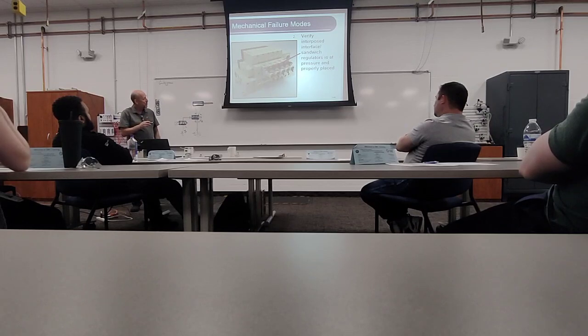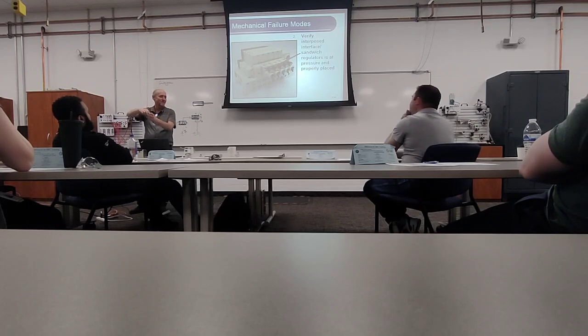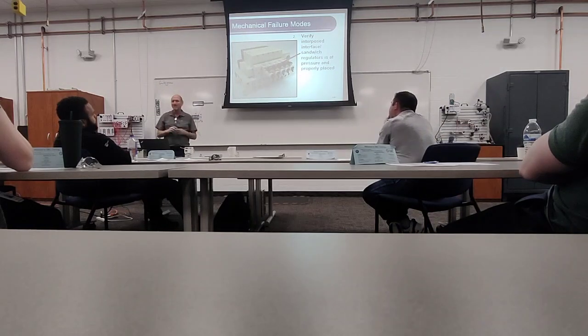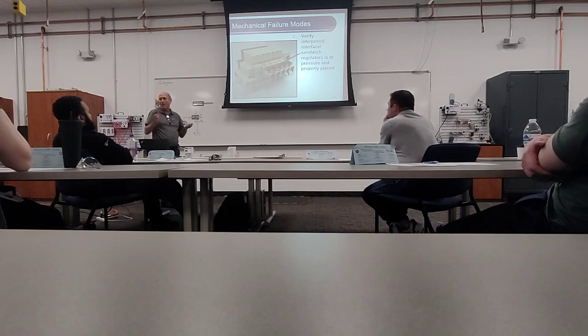And then you can have these, which are called isolation. These are kind of nice. What they do is allow me to turn off the air to that valve, replace that valve without turning off the air to the entire process. So for most manufacturing processes, I don't care, but I made Prozac. I owned the process at Eli Lilly that made Prozac. It was $500,000 a batch. Did not want to drop a batch, right? It took 2 days to make it, and if all of a sudden something failed in the middle of that, I don't want to shut that down in the middle of the process. So you can shut down that one valve, replace that one valve, and then put it back into service without shutting the entire thing down. It's probably not necessary in all places.